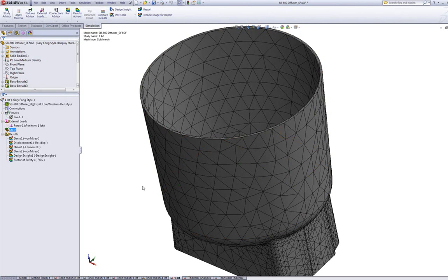So as you can see, if I have a bolt, or just an array of different fasteners, I have to apply many different nodes of calculation onto these small, tiny surfaces or the volume, and this could eat up a lot of your RAM resources. So again, this is why we idealize our simulation studies as much as we can, and then once we have some good initial results, you can go in and add more complexity to your study setup.